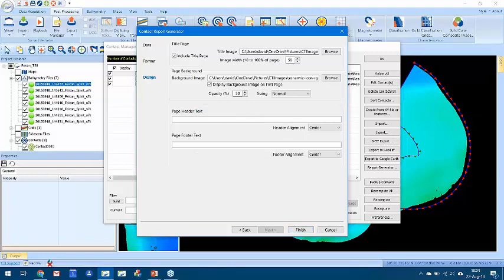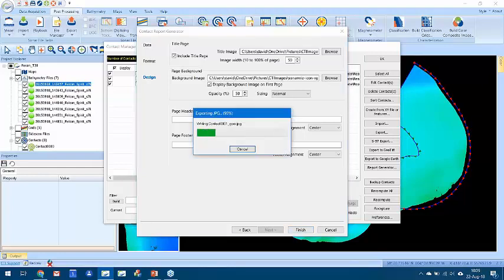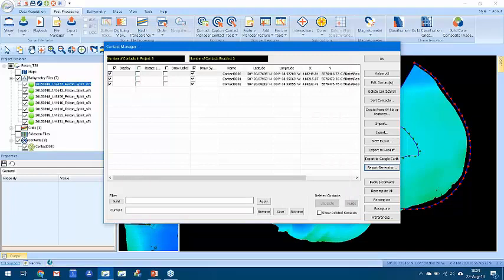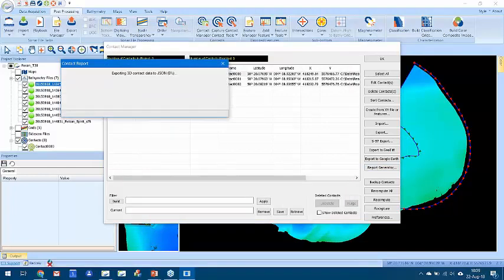Now, exporting this takes a little bit longer, because what SonarWiz is going to do is look at the footprint of the target that you picked out and clip out the bathymetry from that track line, extract it, and put the 2 parts together, so you have a projected version of your bathymetric contact, and you'll have the point cloud up on top of that. And as soon as this finishes, I'll show you what that looks like.